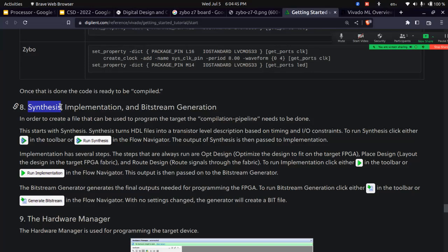It keeps getting into fetch, decode, fetch, decode, fetch, decode. Something happened and it's not working. So make sure it simulates correctly before, and then modify the code so that it is synthesizable. Even after it is synthesizable, it may not be implementable. There are race conditions or timing delays that accumulate so that the clock timing gets different. These were the exact challenges our seniors faced. They said there will be timing errors when you try to implement on a board, and that is why they said it's not implementable.